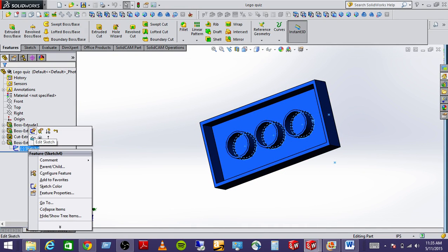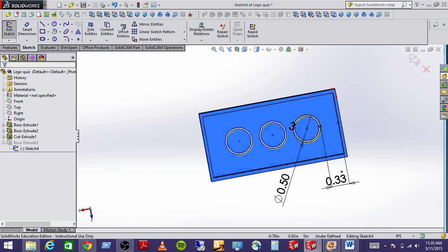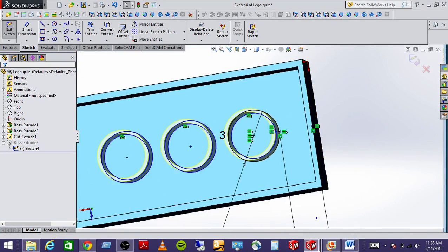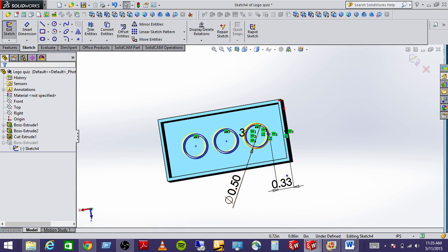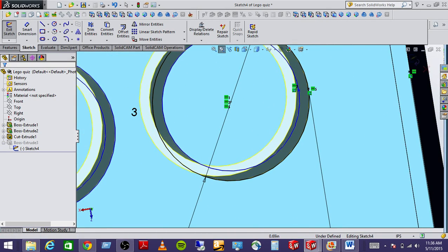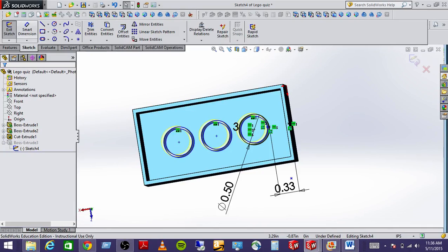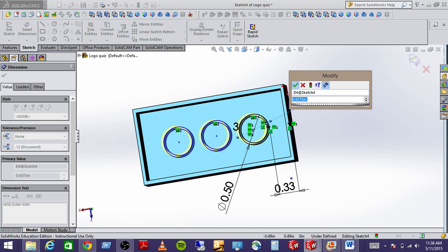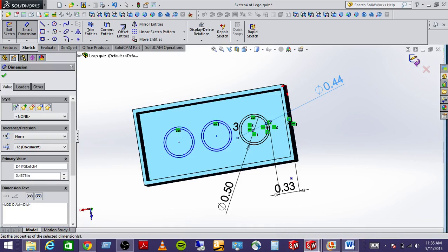I'm going to open this sketch. Check out what I did here. See how I dimensioned this outer circle, but I did not dimension this inner circle? So when I made that thing 10 inches, SolidWorks, for some reason, I don't know why, blew that little circle up into a big circle. All right? So if I dimension this little circle and accept that dimension, accept that sketch,